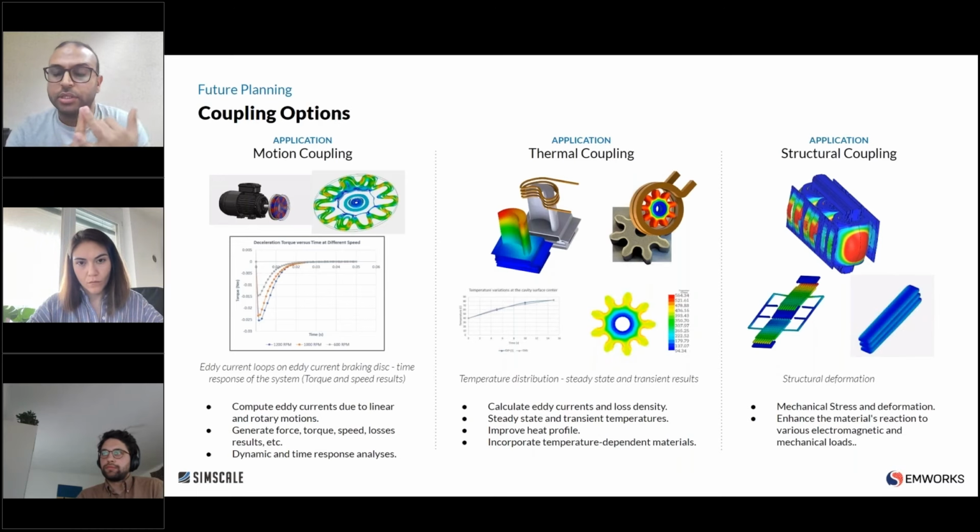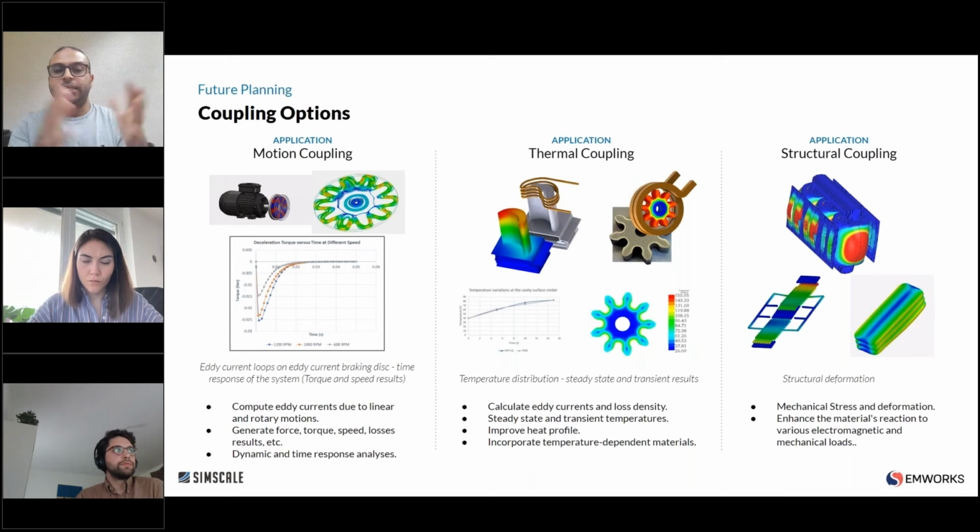So the software, with its coupled capability, can help you to evaluate mechanical deformation due to both electromagnetic losses and electromagnetic forces. So you have the forces without the need to import any data. So it's an integrated solution. You don't need to export loss density or force and use it in a separate tool or on a separate platform to generate these kinds of deformations.